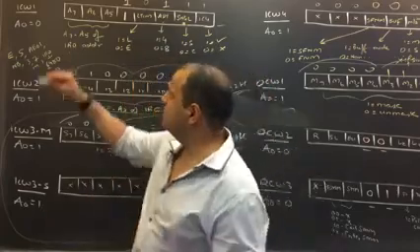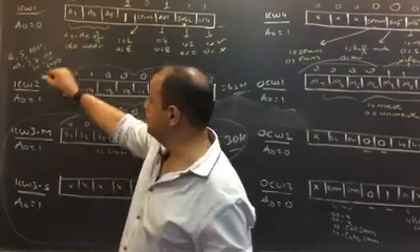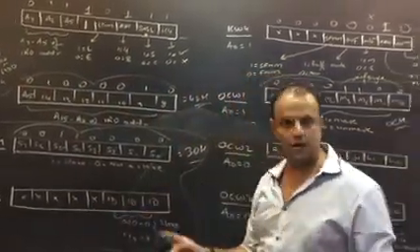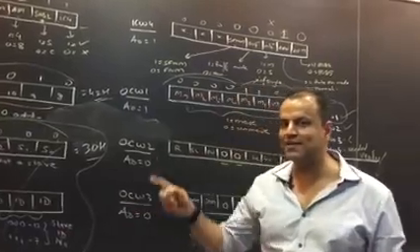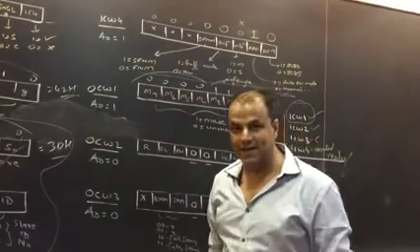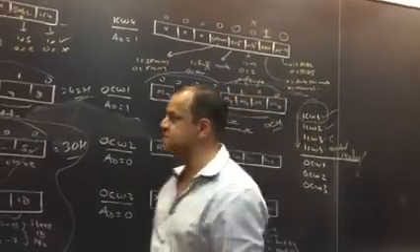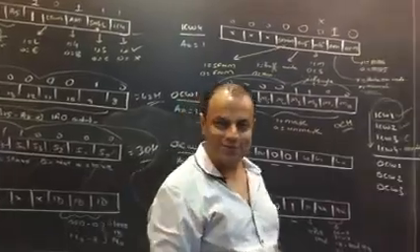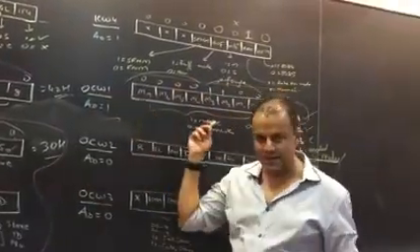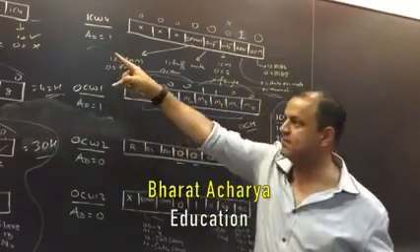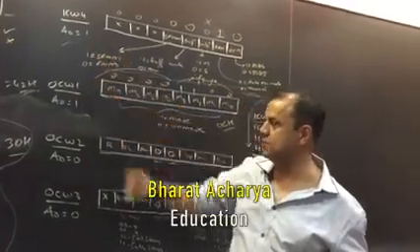Now, do you give ICW1? Yes. ICW2? Yes, because they are compulsory, they have to be given in every case. Do you give ICW3? No. Why? Because it is given for cascaded. The question says single. Do you give ICW4? Yes. Why? Because of that one single specification. Which one? Auto EOI. Because they said auto EOI, that means you have to give ICW4. Masking, yes, they have asked you to mask, so you have to give OCW1. So these 4 commands you will be giving: ICW1, ICW2, ICW4, OCW1.